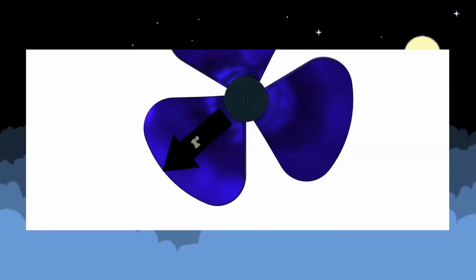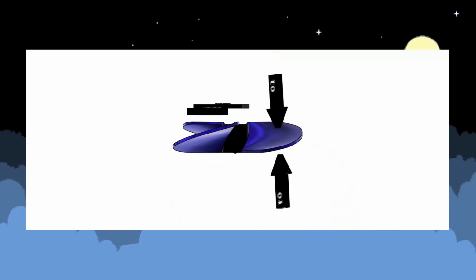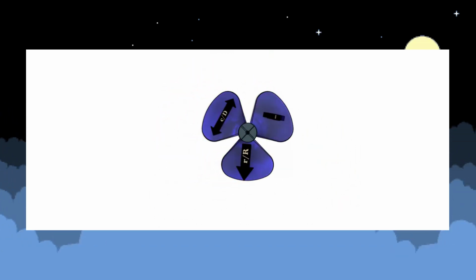The list of values under r/R determines the current position along the overall length of the propeller. The list of values under c/D determines the chord length of the propeller blade with respect to the values under r/R. The list of values under Cd represent the drag felt by the propeller blade with respect to the r/R values. The list of values under t0/D represent the thickness of the propeller blade with respect to the r/R values.